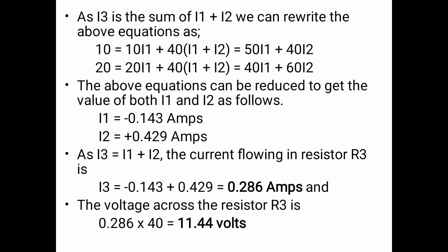And the voltage across this resistance R3 can be obtained as V is equal to IR, that is 0.286 into the resistance value 40, which is equal to 11.44 volts.